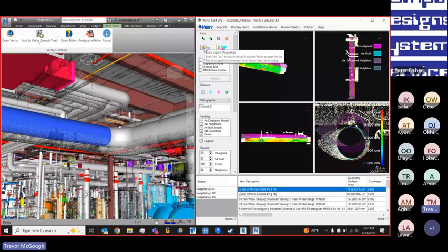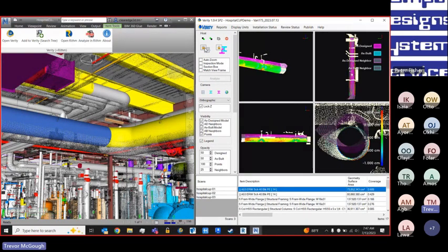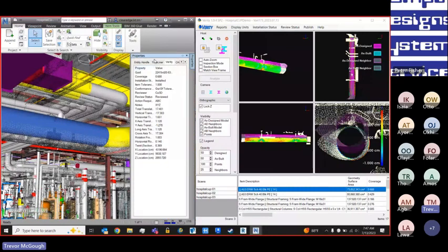The first one will show does two different things. Number one, you'll see it actually color codes the geometry inside of Navisworks according to the tolerance. In this case, my yellow pieces, those represent out of tolerance members. In addition to the color codes, Verity will also go through and actually create a properties tab inside of the element, and it'll push over all the metrics it found, and that way these metrics will now be hosted as part of the properties inside of Navisworks.